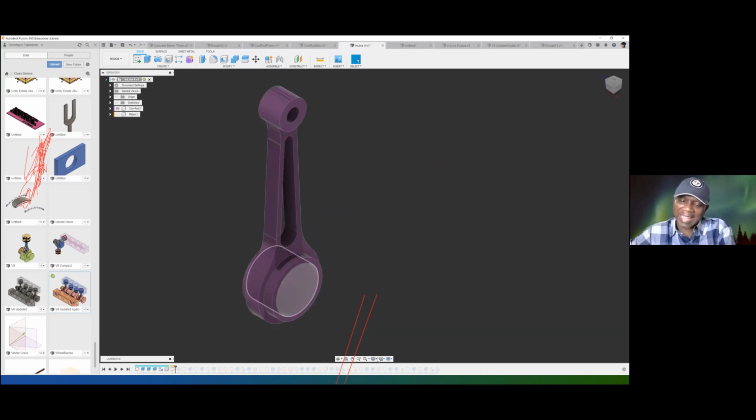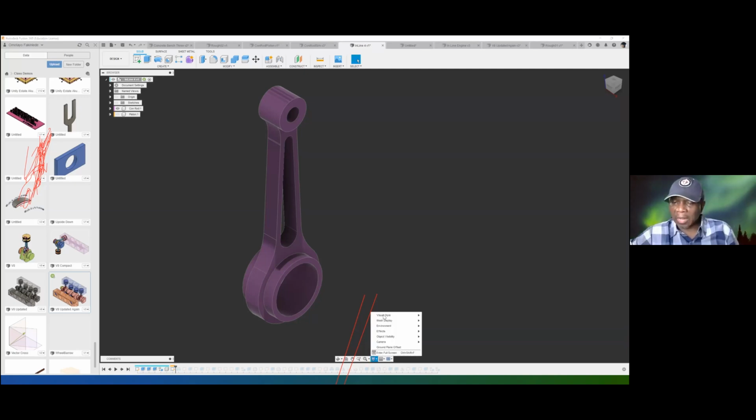The last three icons are settings icons. The first one sets the display. Then you have grid and snap, and then you have viewports. Now let us look at the display settings. In the display settings, you can set the visual style. You can play with this. There are several settings there, and keyboard shortcuts like Control-4, which sets your shaded, Control-5, and so on. The way Fusion 360 looks visually can be changed there. I can't tell you how the others will look; I'll leave that to you to try out.